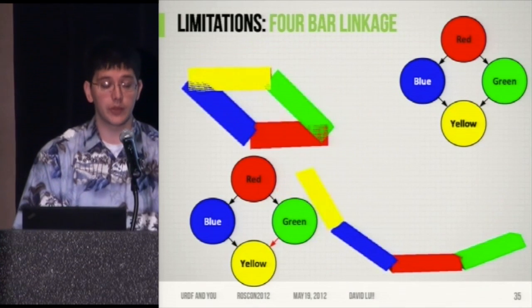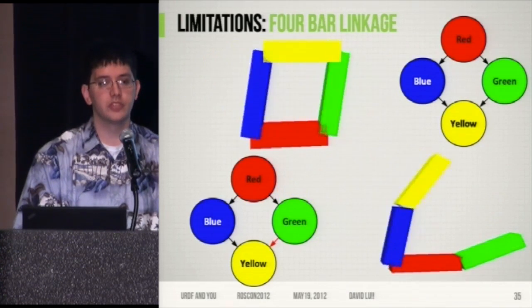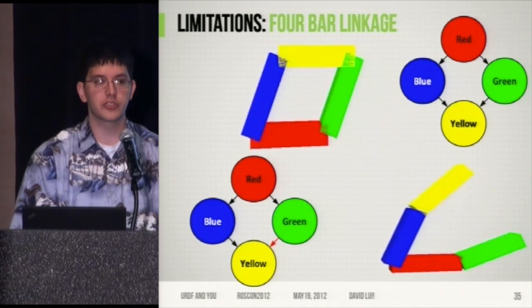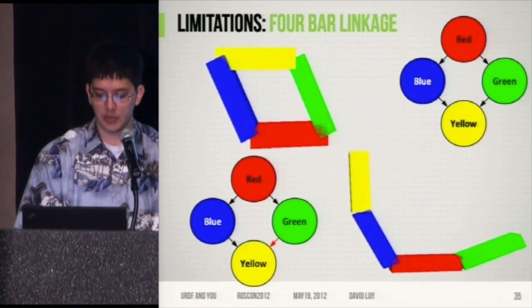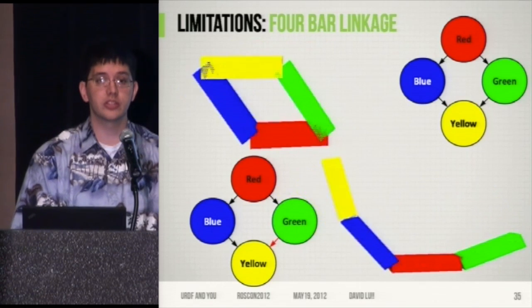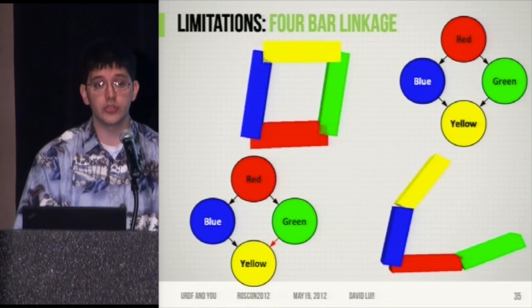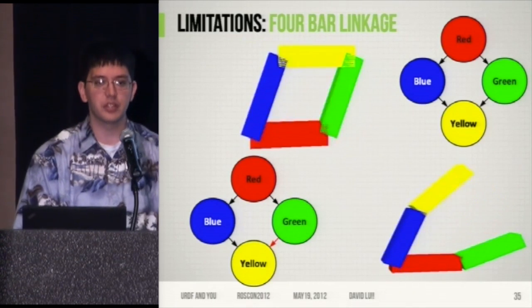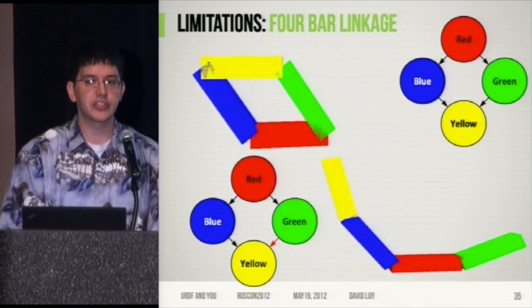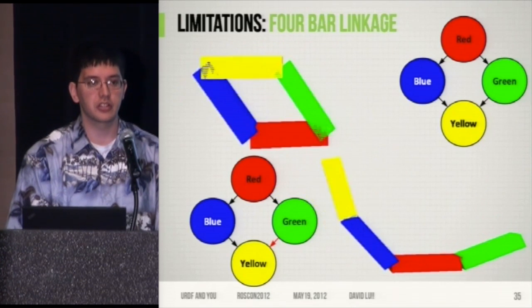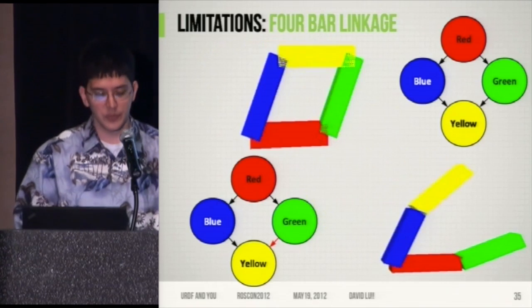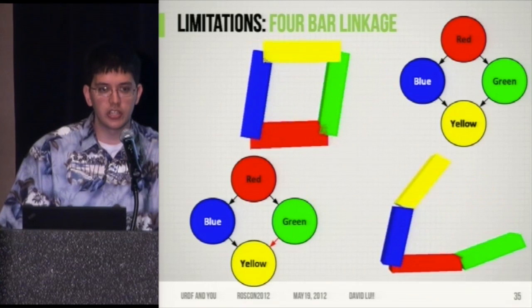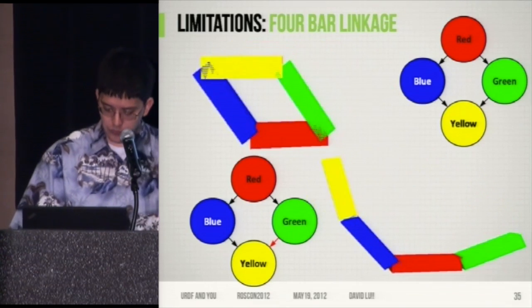There are ways to get around this. One way of doing it is by actuating all of the virtual motors individually using the values from the other ones. You can do this also using joint state publisher using the mimic tag. However, the mimic tag, which has been referenced in a lot of places, I think is actually only officially supported by the joint state publisher node. So you have to use a bit of hackery if you have this kind of structure in your robot.